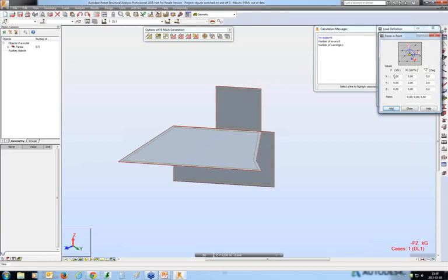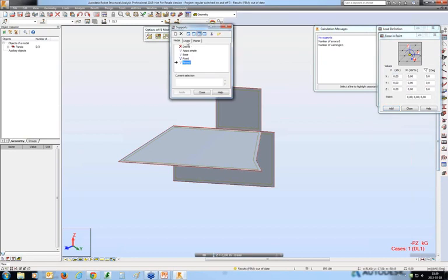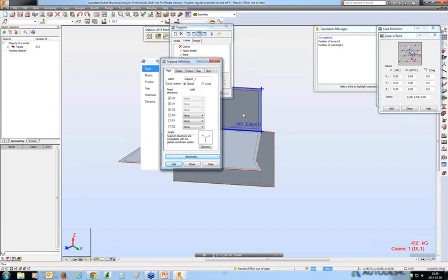The same answer. The only thing is, when you define a linear support and you go to the elastic option, do not mark this checkbox. Then the elasticity will be automatically recalculated for each of the nodes generated along the edge of the panel, depending on the distance between the neighboring nodes.